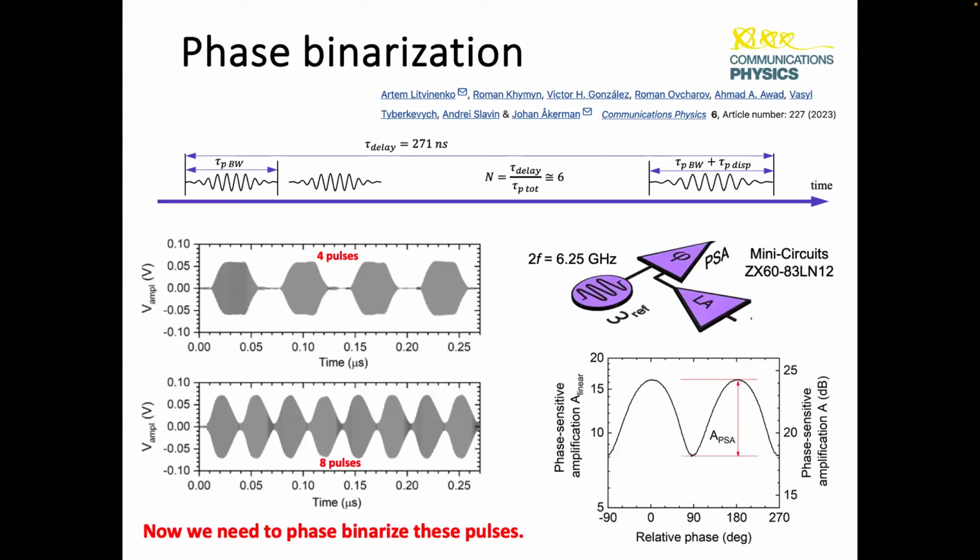We're going to use an amplifier that is meant to amplify the fundamental frequency, but then we're going to pump it with a second harmonic of that frequency. And you can view it naively maybe as the amplifier will choke with the frequency of the 2F signals. So it will be better at amplifying the fundamental frequency at phase states where it's not choked by that 2F. Or in other words, this is a parametric amplifier. It's parametrically pumped by an external signal at 2F, and that leads to a phase-sensitive amplification, which is substantial here